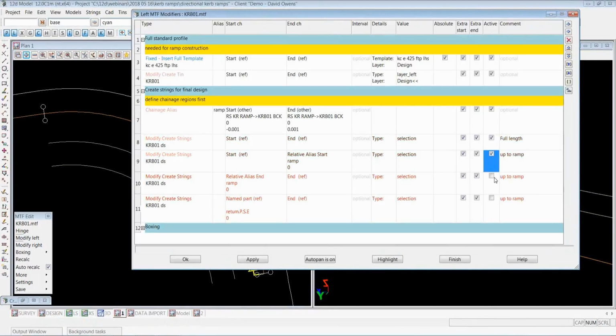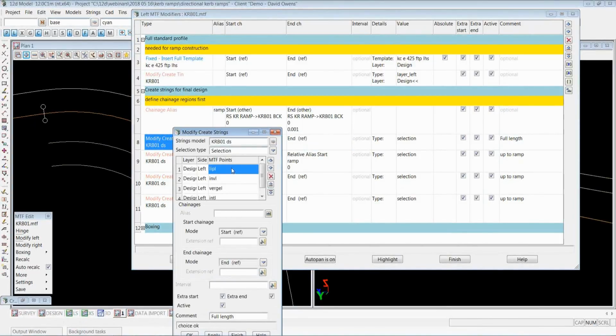And that's why the next bunch of commands here are simply create string commands. So I'm just going through and saying, just turn all these on. Could have done it globally, but it's only a few. So the whole idea is we're now saying that there are certain links from that template that I want to turn into a string for the entire length of this curve return.